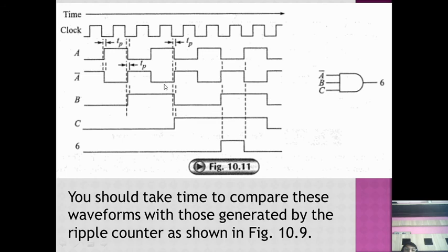In the same way, on every second, fourth, sixth, eighth, etc. negative edge of the clock pulse, the output of flip-flop B results after one propagation delay time. Similar things happen to flip-flop C. Every fourth clock pulse is available to flip-flop C. So on the fourth negative edge of the clock pulse, flip-flop C is toggled, but the output results after one propagation delay time.